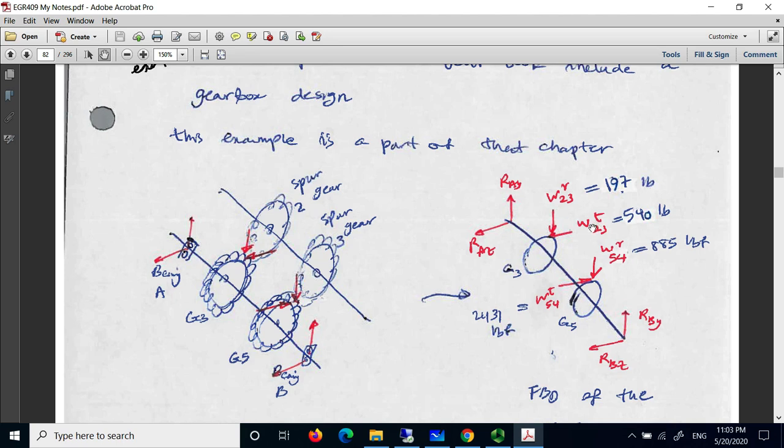But for the other force, the tangential force, you see we have a diameter of the gear here, and if I move it down, I'm going to miss the moment, the torsion, but that piece is not going to affect my deflections due to bending moment. So that's why I neglect that. I'm going to skip that.